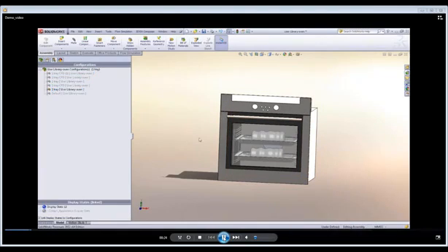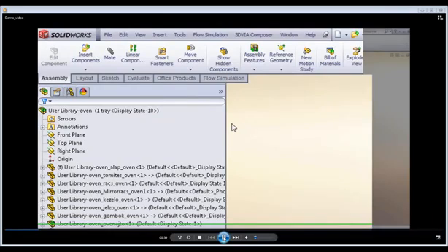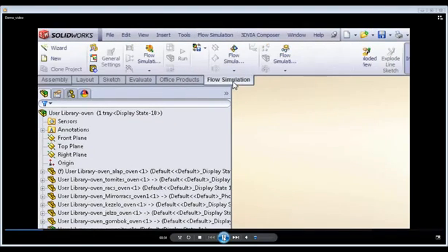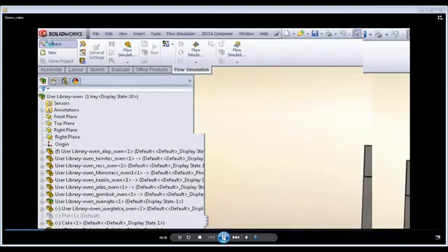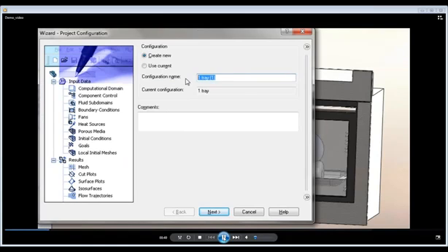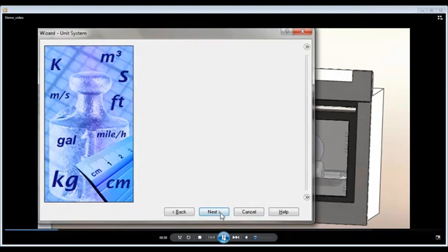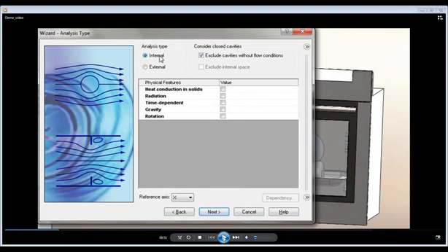Here in SolidWorks, two configurations have been defined, as you can see. So first, let's take a look at the configuration with one tray. With an intuitive wizard, the CFD analysis is set up. The CFD analysis name is defined, so for example here we'll call it Study 1. Then we'll define the default unit system that is predefined in the SolidWorks Flow library called the engineering database, and you can fully customize it with your own unit system, for example. Then we'll define the default assumption.